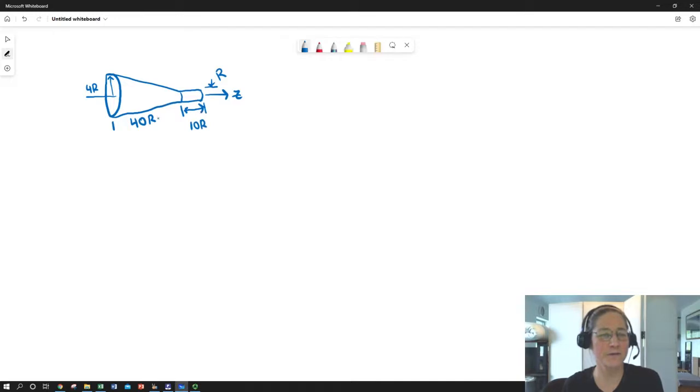So here are our different z lengths. In our stepped shaft, these would have been the lengths that corresponded to different radii. In this case, rather than having single radii within each of those sections, we've got one where the radius is in fact dependent on our position axially, because it's a tapered shaft. In fact, it is dependent linearly. So we can make a little equation based on a particular position down the shaft.